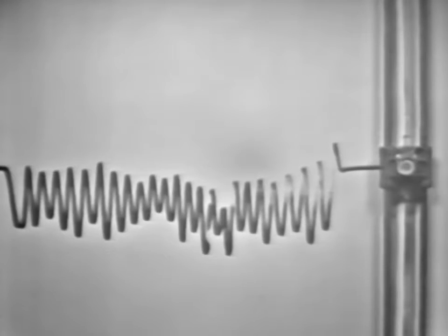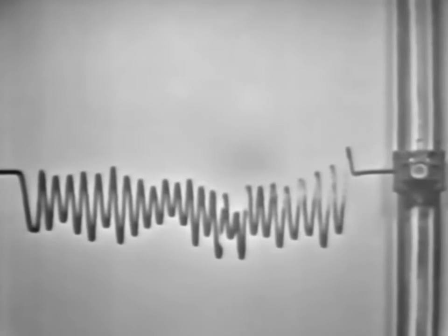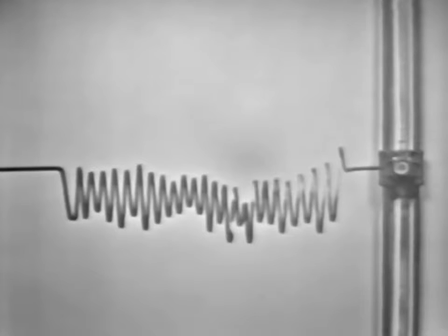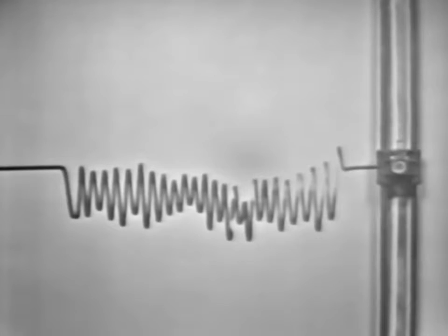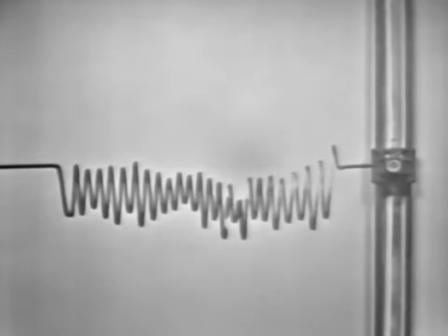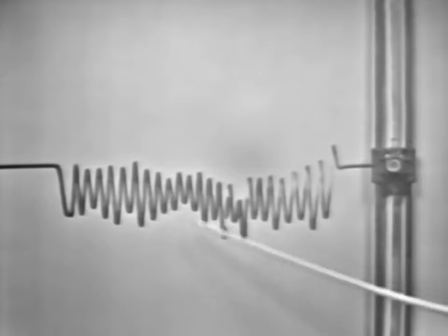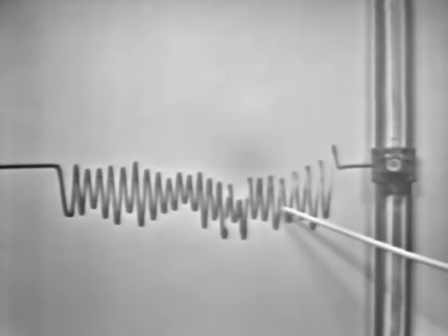and if we could add it in the proper amount, we would have a waveform of constant amplitude and constant frequency. Our graph shows us that this method produces a waveform of almost continuous amplitude and stable frequency. This is essentially the wave shape we want out of the LC oscillator. Constant amplitude and constant frequency. Of course, this graph does not show that by any means, but it does illustrate the point.